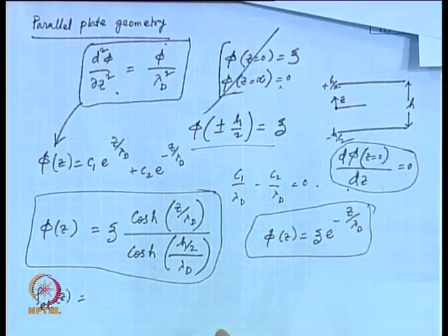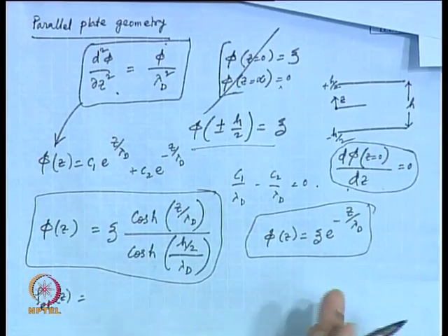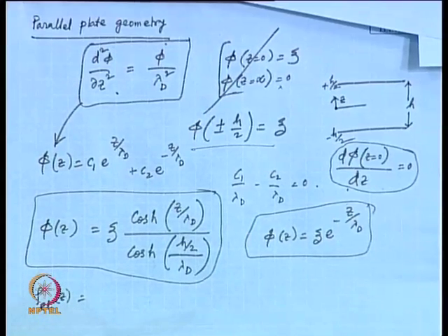So, you must have seen the thought process here. You have defined a potential, you have to come up with rho E L, which is basically the charge density, and then you introduce that in the body force term in the Navier-Stokes equation, and only then can you come up with an expression for velocity. Then you can say, okay, this is the electroosmotic velocity you can expect in electroosmosis for a channel formed between two parallel plates.